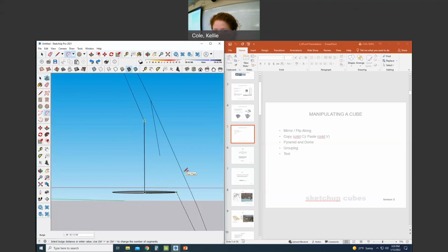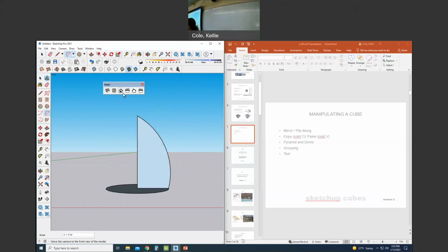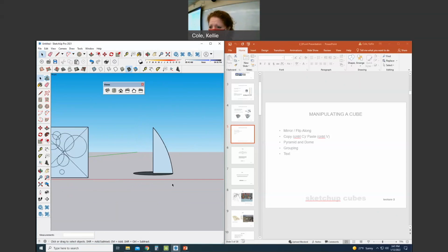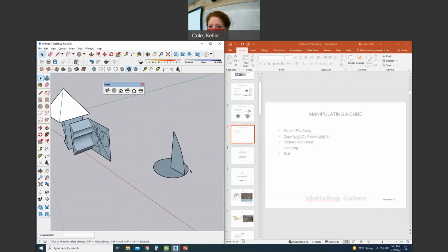Okay. We can always try to work in, if we use our Views tab and go to Elevation, that'll put us in the perfect elevation. It has to be a solid surface. Okay, so now, and this actually didn't work for me the first time I did it in class. We'll see how it is for you. And then I got it to work. I am going to click that sail-like surface we just created.